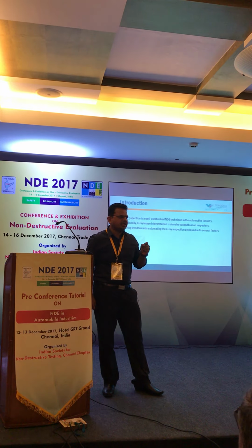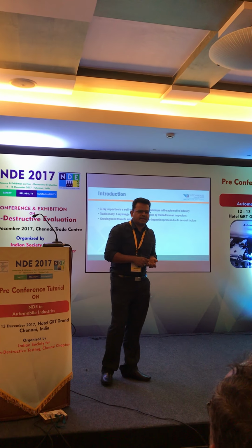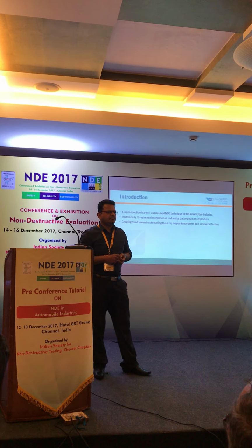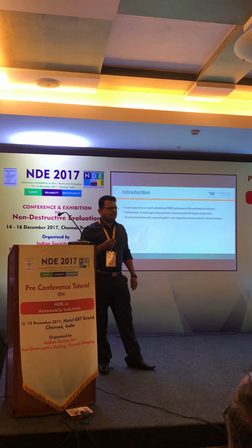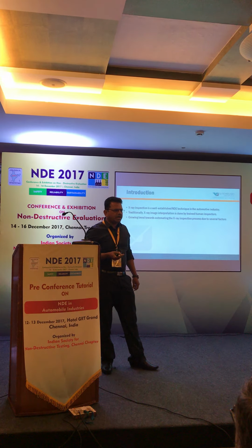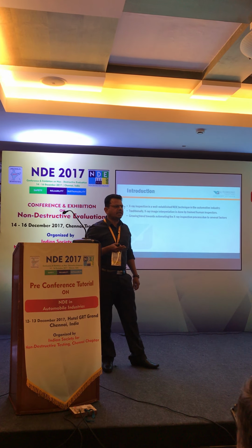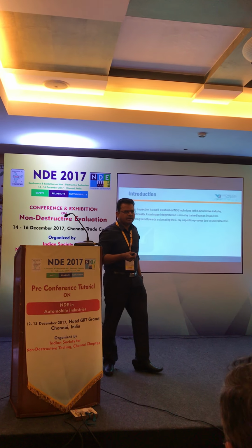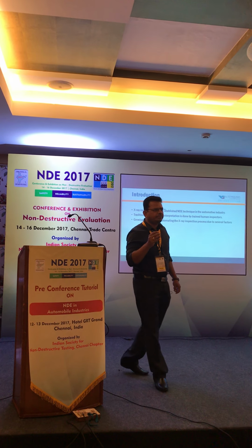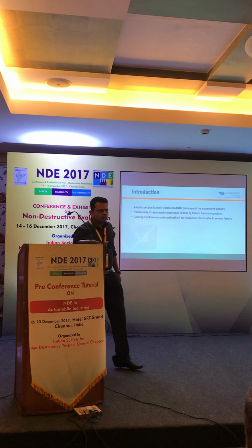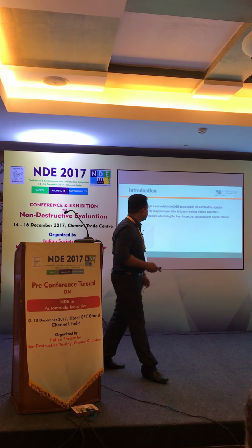He is inspecting a casting part or a welding part, and needs a little knowledge of castings. We have gas holes, shrinkages, porosities. So he needs basic knowledge of why the porosity occurs, why the shrinkage, why the gas holes, and what type of welding, and whether it is the same type of defect in the weld. If he knows the basic characteristics of the material or the weld, it will be easy for him to interpret the images.